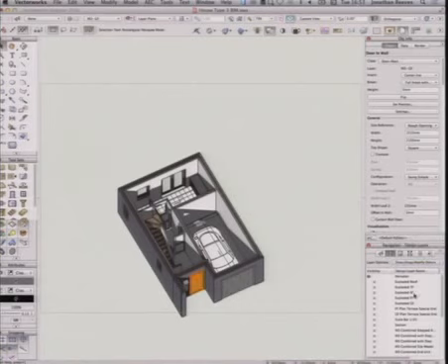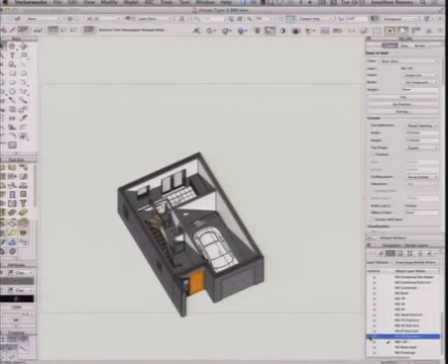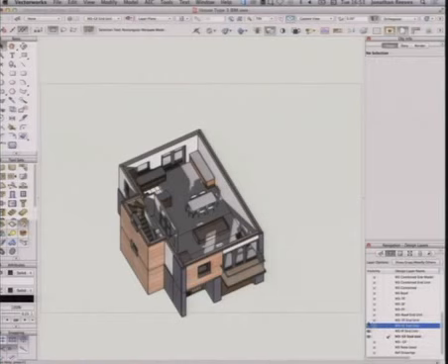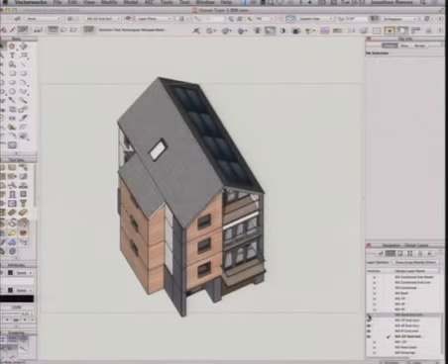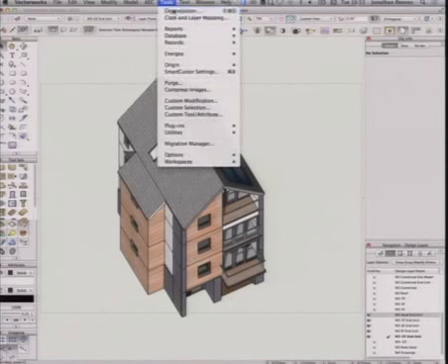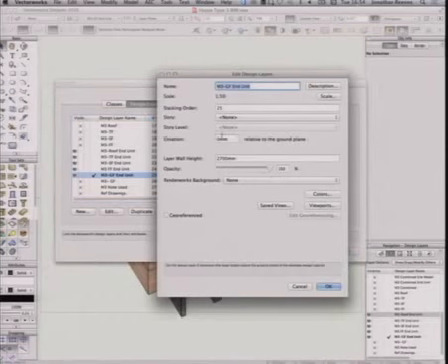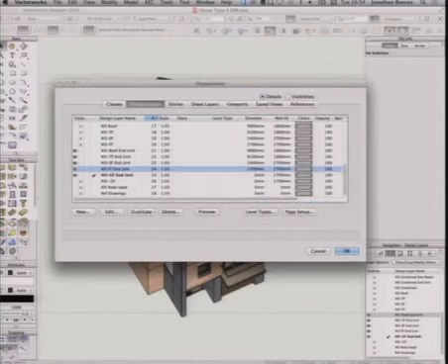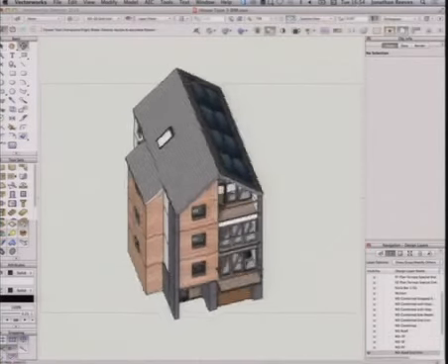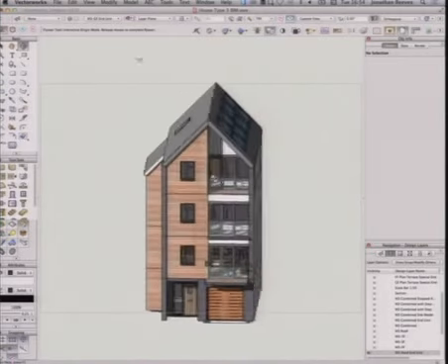Okay, let's go to my other layers and turn on the upper layers here. In fact, I'm going to swap over to this end unit. This is a slightly different layout. I'm just building up the building layer by layer. That's all I've really done on this project. Very straightforward. The organisation of those layers is simply that they sit one on top of the other, 0 to 2700. The next layer starts at that height and goes up. So think of a layer as a thickness of space to draw in, not just a flat sheet of paper. Okay, so hopefully you can see what looks like a nice little model there.